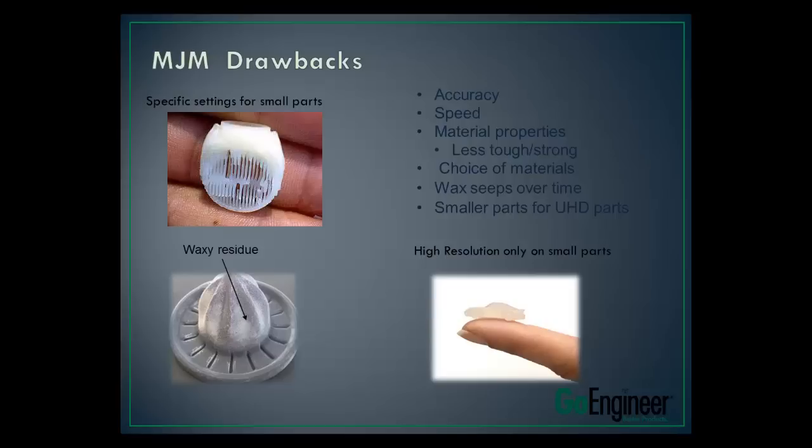The process is very time consuming just because it lays down such fine layers. You pay for that fine detail with time. And the build time greatly increases with the size of the part. You can just imagine you're putting down this small layer, you're making a car like there on your screen in the lower right hand corner. It's not going to take that long. You're going to make an orange juicer there. It's going to take a very long time to do.